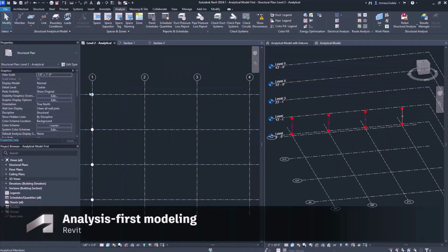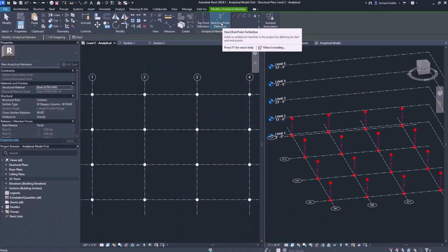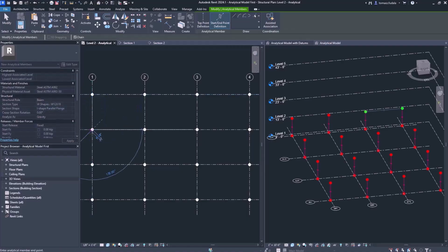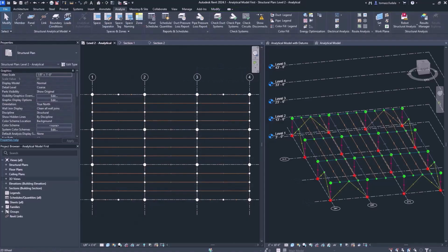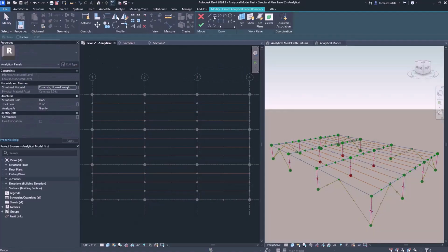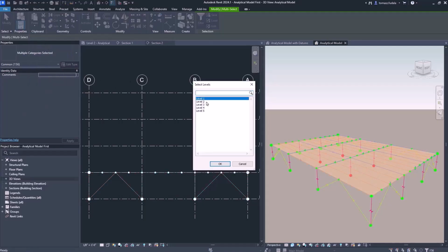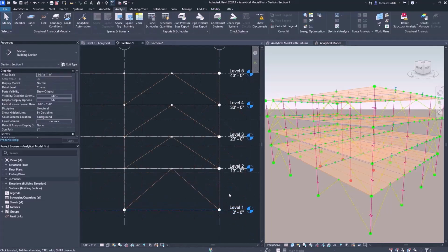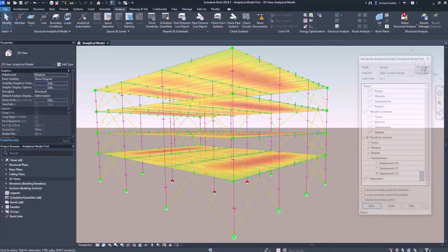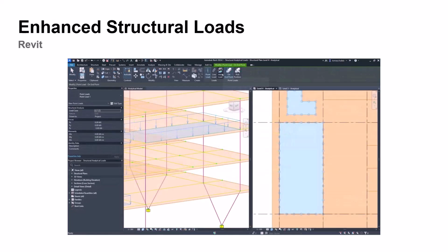And as the analytical model is completely autonomous, it allows structural engineers to initiate structural analysis workflows from Revit without any physical geometry. Instead, they can start a new model from scratch and focus exclusively on aspects of analysis. So engineers can start modeling with analytical geometry and simply add some physical geometry when needed for the construction, documentation, and detailing phases. This workflow is especially well suited and applicable to projects where engineering requirements dictate the design.